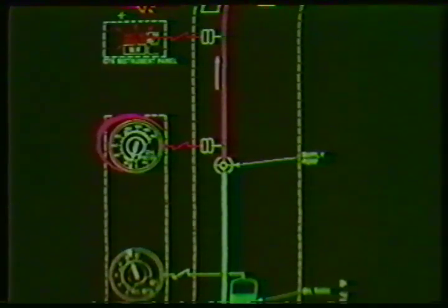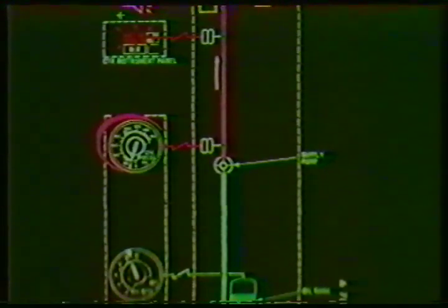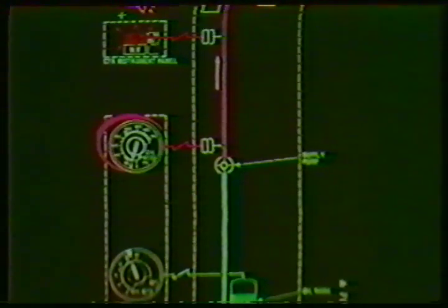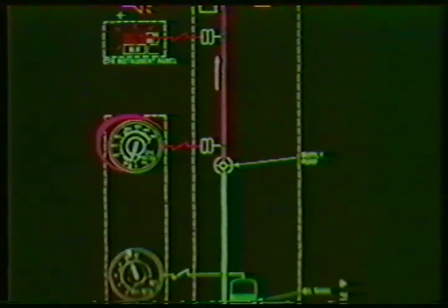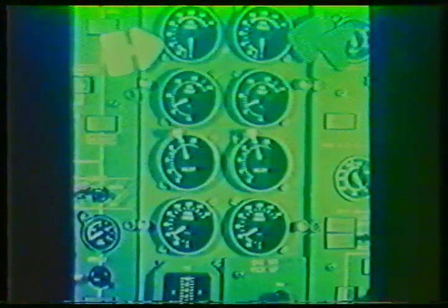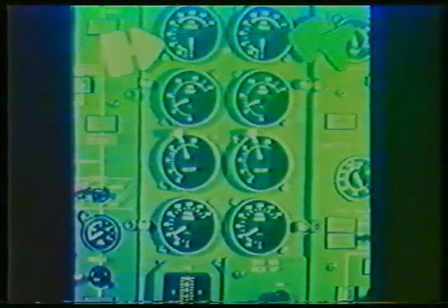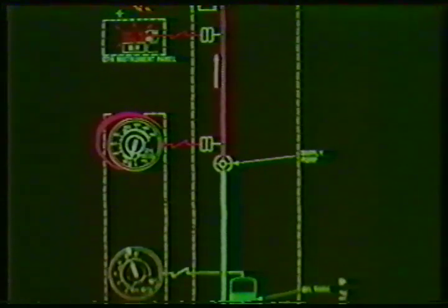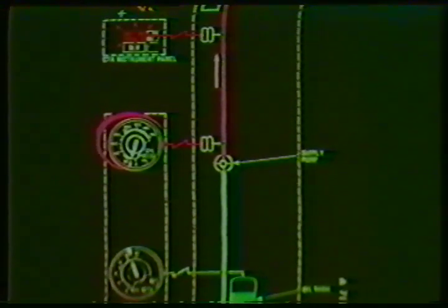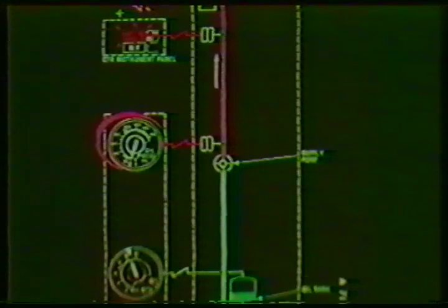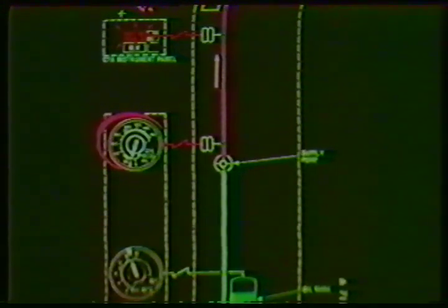After the supply pump, the pressure is sensed and low pressure will be indicated by an engine oil pressure low red light on the master warning panel, accompanied by a single stroke chime. Oil pressure is shown by an oil pressure indicator on the second officer's panel. Notice that the oil pressure and the warning light receive their information from two different transmitters. Oil pressure is a function of N2, and the engine oil pressure low warning comes on when the oil pressure is lower than 10 to 12 psi.